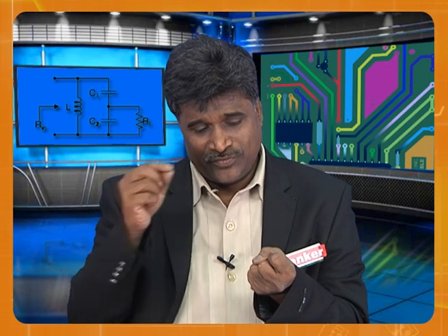They are the Thevenin's equivalent, Norton's equivalent of a big circuit. Let it be a telephone or let it be a loudspeaker. Even if you connect the loudspeaker to a very big line, you have to see the equivalent. If this impedance and that impedance are matching, then only the maximum sound will come.